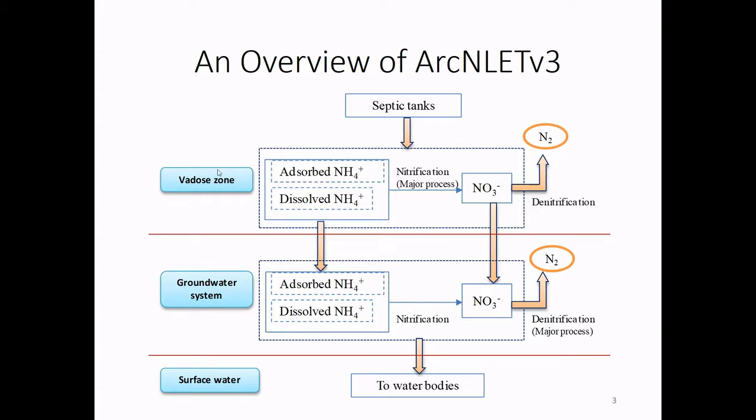This is for VZMOD. And for groundwater, the dissolved ammonium and nitrate flow into groundwater. And also we simulate adsorption of ammonium and nitrification of ammonium and denitrification of nitrate, and whatever is left will flow into the surface water body, and that will be our load.